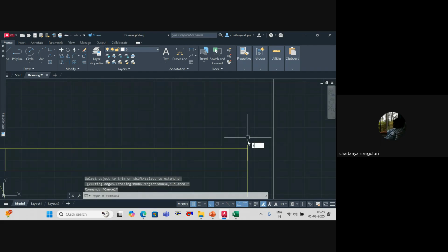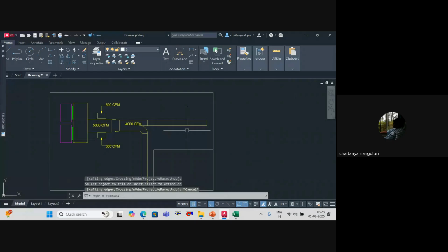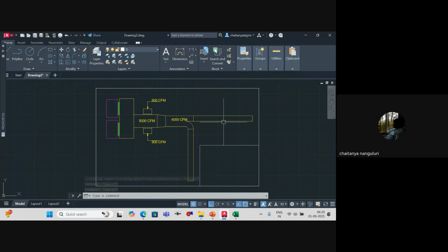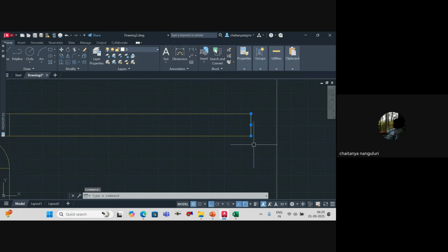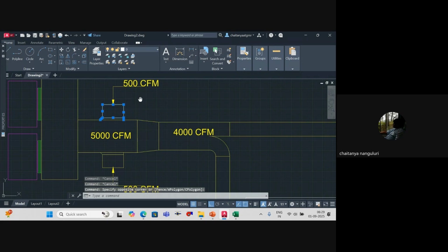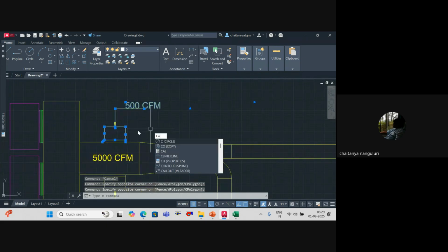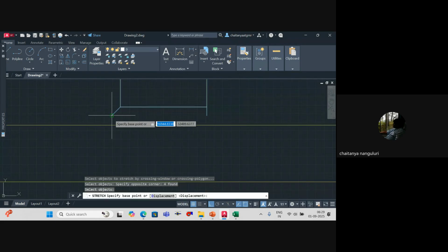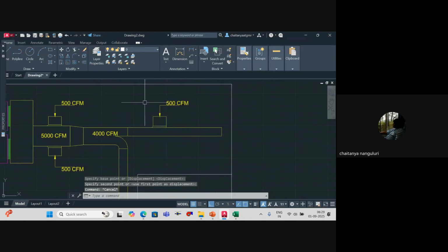So now at the end points, you have to close the duct. Else what will happen? Instead of here, all the air will be dispersed over here. You agree? So for that reason, we have to close the duct, and we call those dummy pieces. And then we basically provide some collars. Let's say this is one collar; for 2000 CFM, probably I can go for some four numbers.